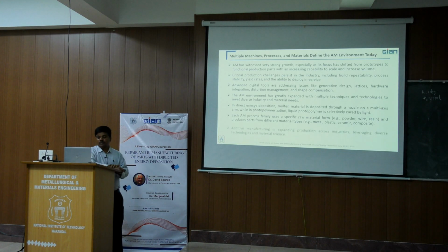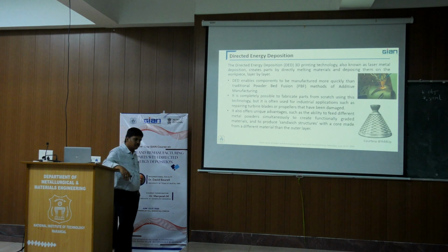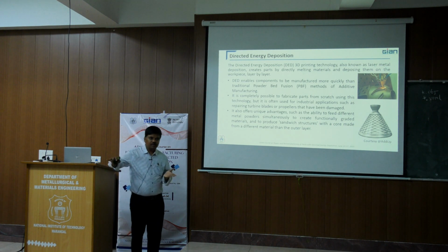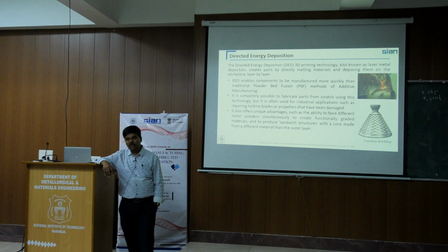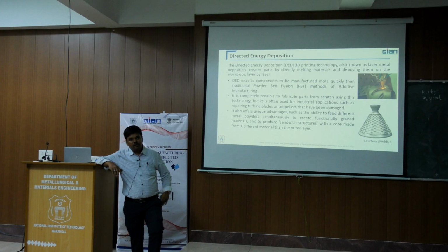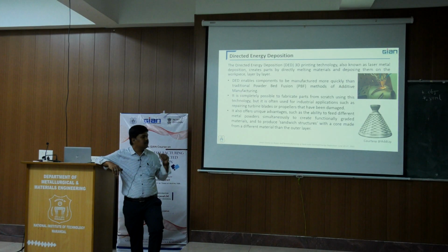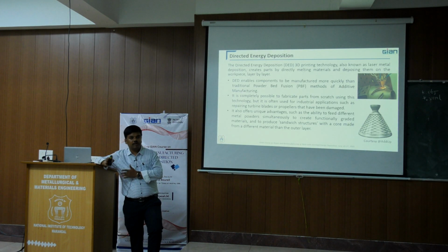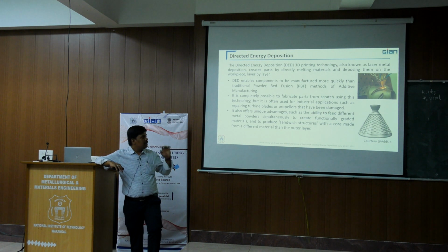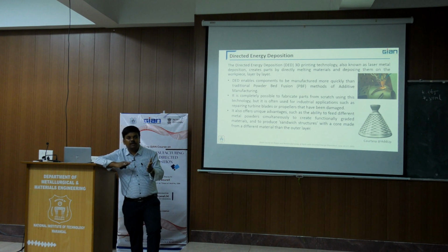Even in the DED process, the direct energy deposition process, we have several categories. We can use arc, or we can use laser, or we can use an electron beam also. But not all 3 processes are suitable for all applications. Where do we have to choose your laser DED process, where do we have to choose your arc-based DED process, and where do we have to choose your electron beam manufacturing process? All the concept and the mechanism is the same, except we are using different energy sources as well as different feedstock materials.